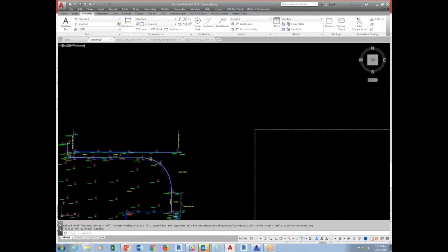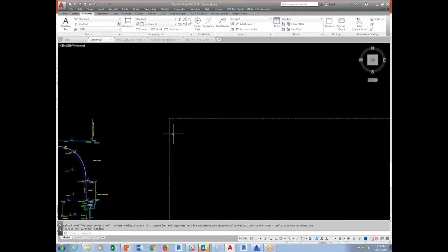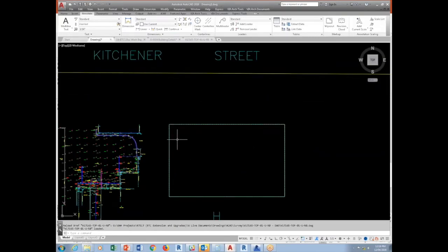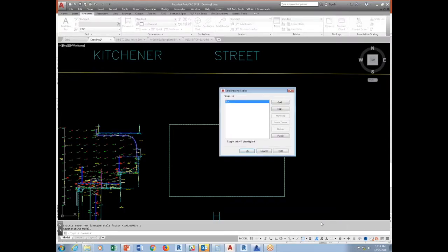All right, so when I reload this, you notice that the line type is really, really small. What happened in the past is that people tend to do this: LTSCALE, say we want to make it 100. Okay, that's how we did it. In the new way, don't do that. In the new way, you have to use this scale to drive your annotative objects, similar to how Revit does it, right? So we want to encourage people to use this.